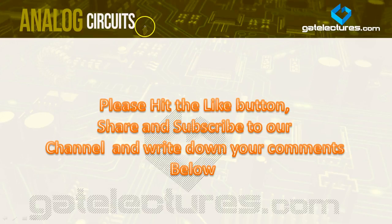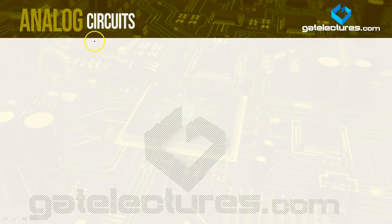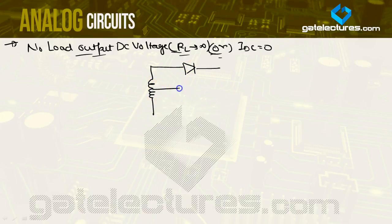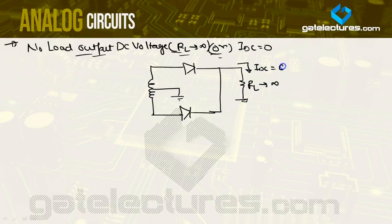Now, we basically ended our last lecture with the discussion of the V diode DC voltage. Now we are going to discuss the no load output DC voltage, when we take RL infinity, or we can say that IDC is equal to 0. Since we are performing the DC analysis in this case, we look at the second part of the circuit. We are considering only one diode at a time, and RL tends to infinity, which means that IDC here is equal to 0.